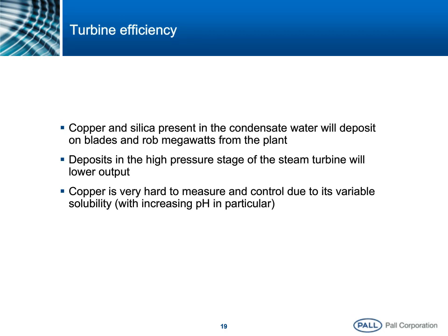Silica in the same way is a specific challenge for other reasons. It usually comes from the outside. Very few components internally have silica in them. So it's usually a sign of either makeup water coming in that's not up to par or some leaks in things like the condenser tubes, for example. And silica also will be found in many forms in the system, both dissolved and colloidal forms.